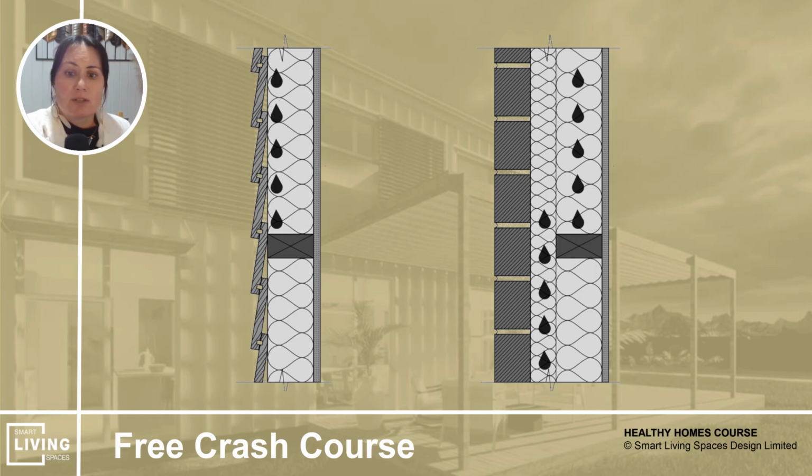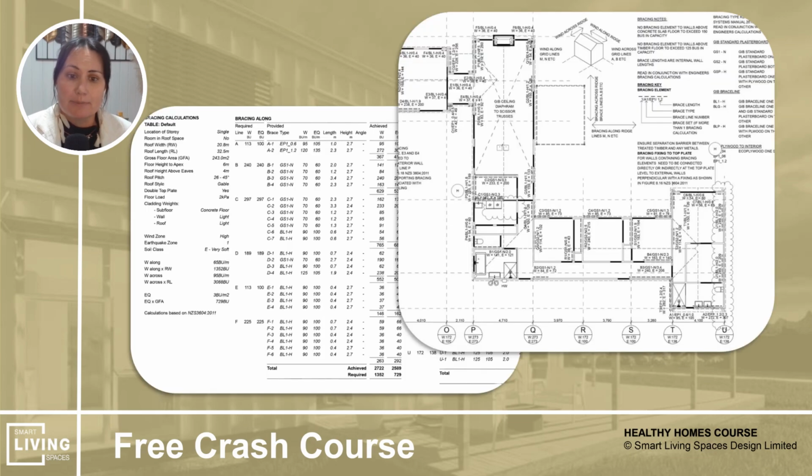Now, here's the reasons for this. One is you can create moisture, mold, and rot issues if the insulation is in constant contact with the back of your cladding, especially if you don't have any building paper, and old homes don't generally do. And insulation can block up the drainage cavities in the construction of our walls, particularly if you've got brick veneer, which again is going to trap water in your wall structure, and you will find mold growing through your wall linings over time, particularly on the north faces where it gets some heat. Now, warm, moist conditions are paradises for mold, and timber wall framing is the organic material to feed it. So it's a perfect breeding ground for it silently.